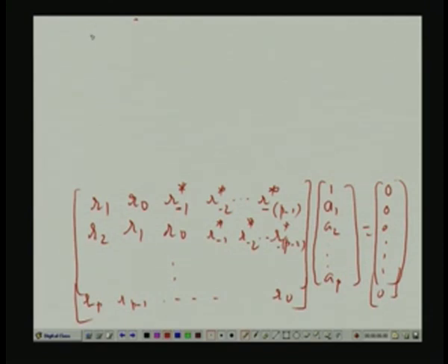just a few lines. What we have, suppose I started at k equal to 1, but suppose I do this E n x n minus k, and I also take k equal to 0 case, k say equal to 0, that case I take. This is no longer orthogonal. E n is orthogonal to x n minus 1 up to x n minus p, this is not orthogonal, then what is it?